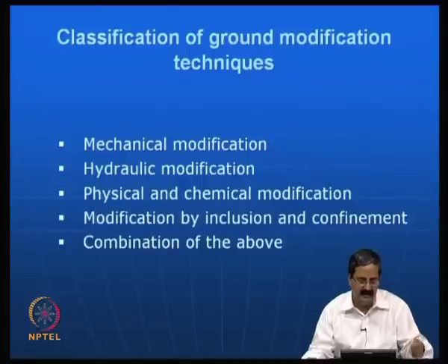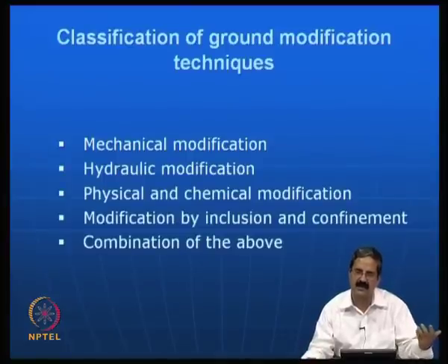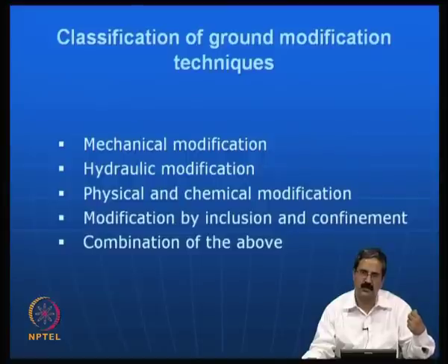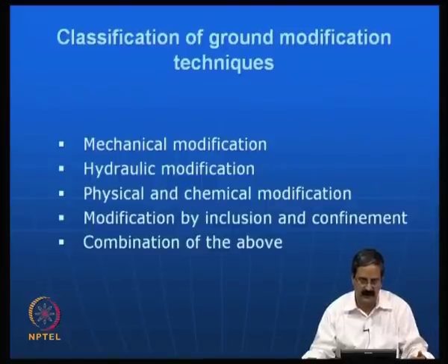Now, by adding some sand, by physical means, the water content variation is brought down to a range from 60 to 20, which means about 40%. From 90% to 40% you reduce the range of water contents, which means that you are able to achieve some sort of stability using physical means. The same thing can be obtained in the case of expansive soil using, for example, lime. Lime is a classical technique in stabilization of expansive soils. So, you add lime and it reacts and forms cementation bonds and many other things, with the result that even chemically the same process can be obtained.